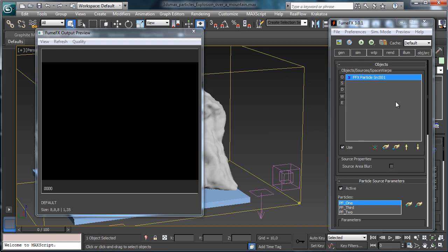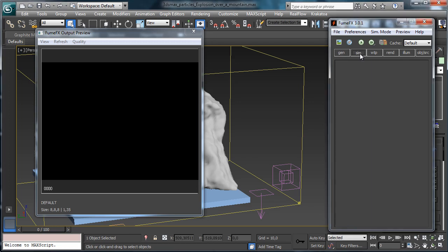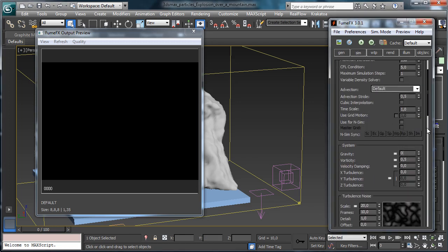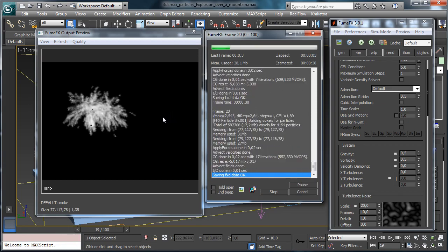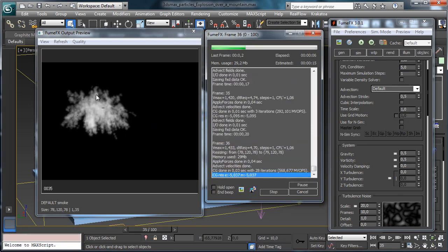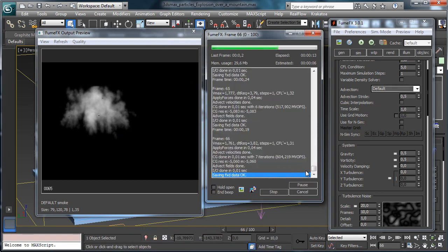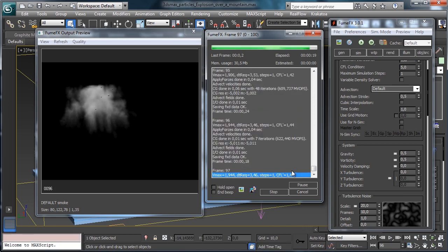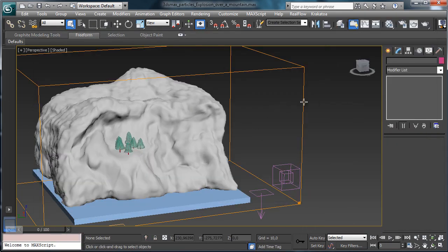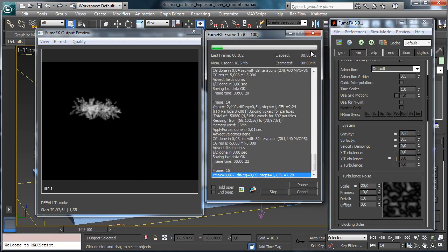Okay, so I like to tune also some various parameters there. And the first thing I like to do is to change the gravity. We'll have less gravity. Let's go to 0.5. Having less gravity will give us less dynamic, so you see the growing up of the particles, because we are generating a different way of simulation. So for example, we can decide that the smoke there is not bad, and to do something like that we can decide to have still less gravity. Let's try with 0.25. Let's recheck.